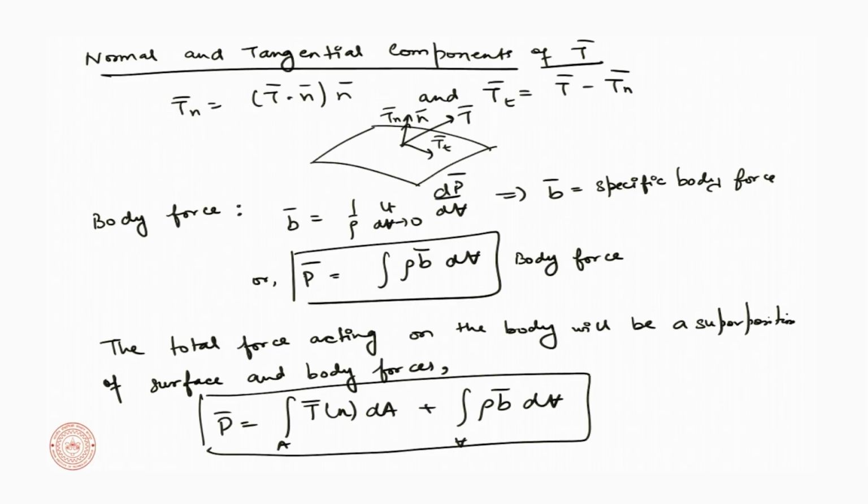But so far, just to realize that we have a traction vector, that is force per unit area on a given surface. It can be any surface. It can be this curved surface at the end, this top cylindrical surface. We can make an intersection at a plane, and on that plane we can find the traction. Any exposed surface, we can find out the traction, and the traction multiplied with the area will be our surface force. Our body force, the density of the body multiplied and integrated over the volume, will be our body force. Summation of the two forces will give us a net force.